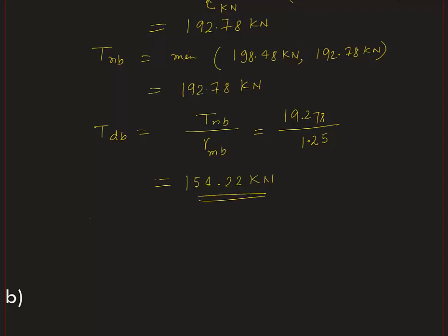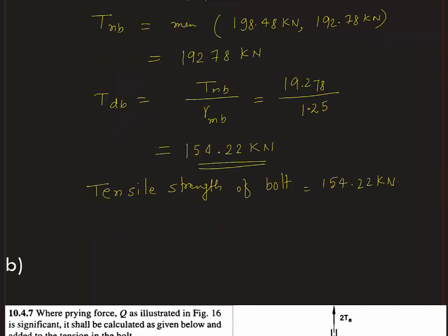So this is the tensile strength of the bolt, that is around 154.22 kilonewton. So we can say this is the design capacity that is asked in the problem.